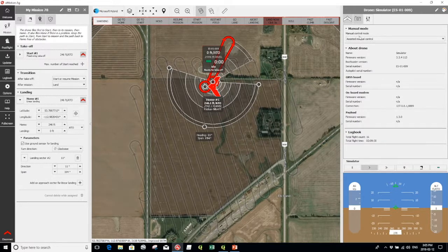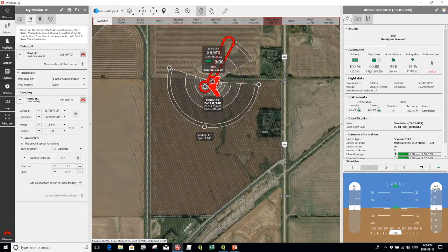This is the important one here, this manual control. So the Sequoia does come with a hand controller that you can use to move the drone. Like in the event of an emergency, you can control the drone without using the computer. I would recommend leaving this assisted manual control on. The full manual control can be quite hard to fly, where this assisted manual control will only allow you to bank so far and climb so fast, so you prevent the drone from stalling or crashing.